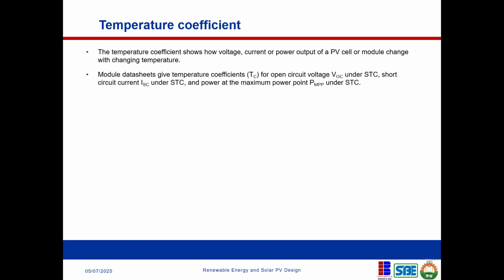Okay. We are still talking about temperature coefficient, and what that simply means is that once the temperature of your module increases, it reduces the voltage, and once the voltage reduces, it also reduces the power output. So that's just the simple explanation. And what this temperature coefficient is trying to tell us is that for every rise in temperature, this is the amount of power you're going to lose. For every increase in temperature, this is the voltage drop that is going to result.